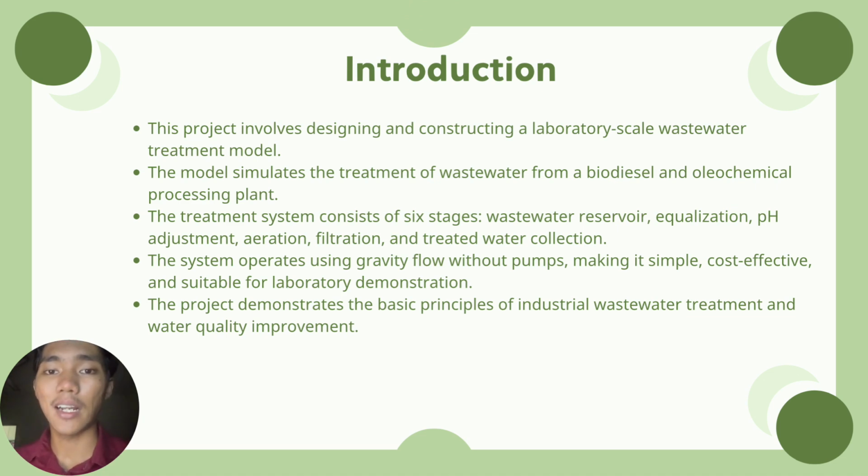So next, I will continue with the introduction. This project focuses on designing and constructing a laboratory-scale wastewater treatment model. The model simulates wastewater generated from a biodiesel and oleochemical processing plant. The treatment system consists of 6 main stages, which are the wastewater reservoir, equalization and screening, pH adjustment, aeration, filtration, and finally the treated water basin.